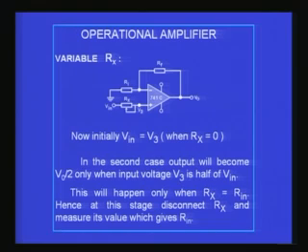So, you understand, you first apply a voltage with Rx equal to 0, measure the output voltage, and keeping the input voltage constant, only change the Rx. Increase the value of Rx till you get half the value at the output. Whatever value of Rx you then find, you should not measure it in the circuit, because there will still be voltages at different points.